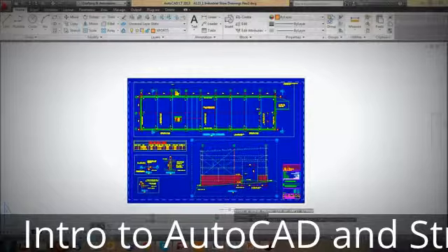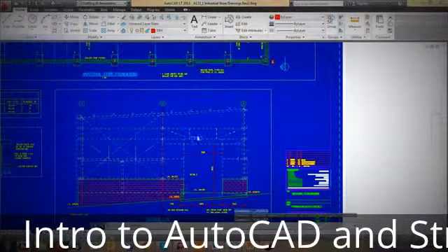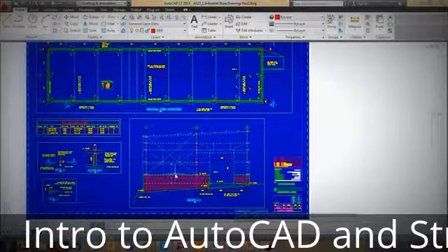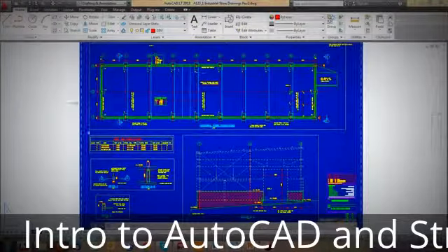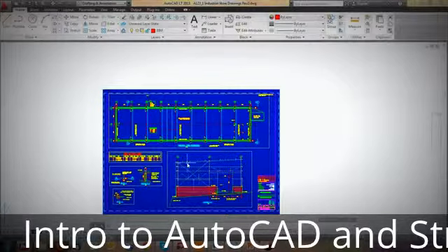All right, what I've been doing was in the command window, and we're going to have a look right now at the command and the ribbons at the top. But before we finish that, let's finish up with viewports. Viewports are windows into your model space. Normally with a drawing, you want to set it up at the beginning such that your viewports are there. You know what you're going to put on the drawing, so you know what scale they have to be.